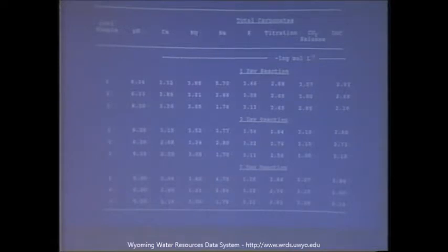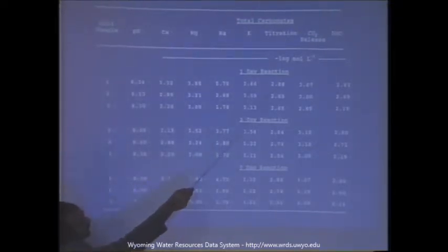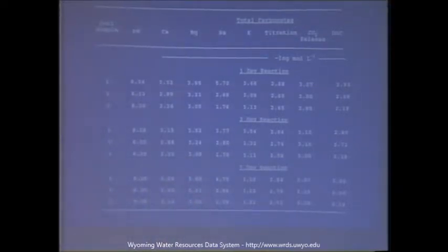When we go to soil 3, we had really high dissolved organic carbon, okay? The calcium concentration also increases as you increase the dissolved organic carbon in solutions when you measure with ICP. Similarly, the direct titration method here also increases carbonates as you increase the dissolved organic carbon. This is true for all 1, 3, and 7 days. Okay?